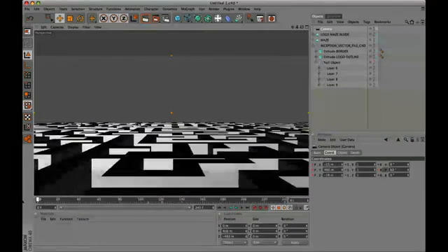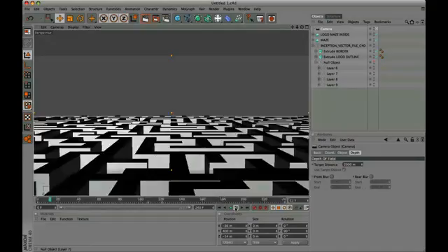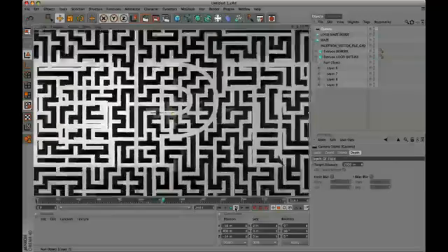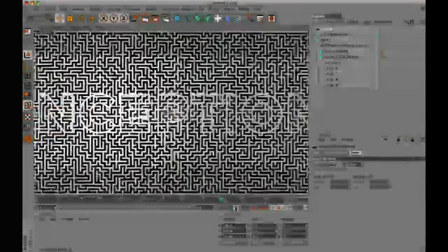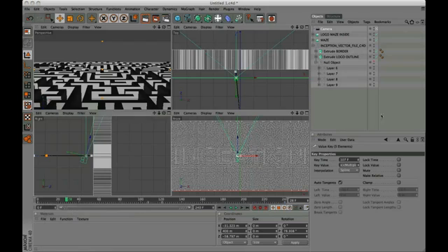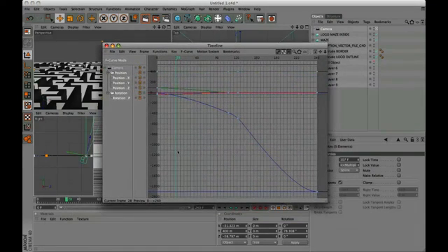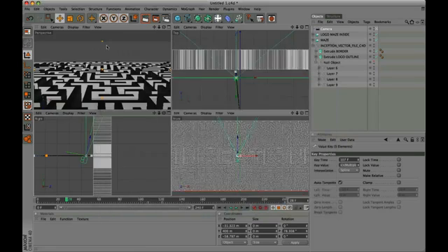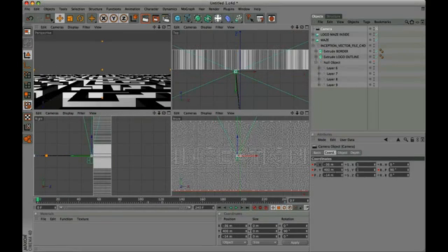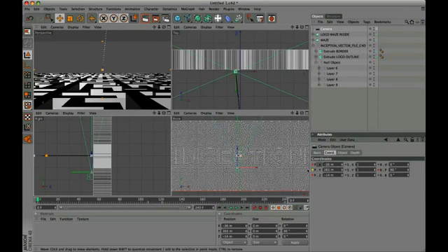To get the result. As we can see, we need to improve the movement of the camera through the F-curves panel. We must make this curve softer, which is very important, to be able to see the inside of the P letter in the first part of the animation. We need to change, at frame 0, the Y coordinates from 400 to 265.